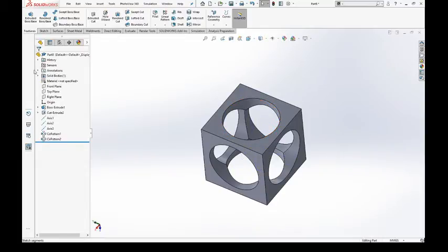From here, we're going to apply some fillets. So in the features tab, we've got the fillet command. However, you'll notice that there's a black arrow underneath it. This tells us that there's embedded commands beneath this. So if I click on this one, I get 2. Linear pattern, I get multiple options to choose from. So anything with a black triangle underneath it suggests that there's something beneath that I can choose as an additional option. So I'm going to choose fillet.